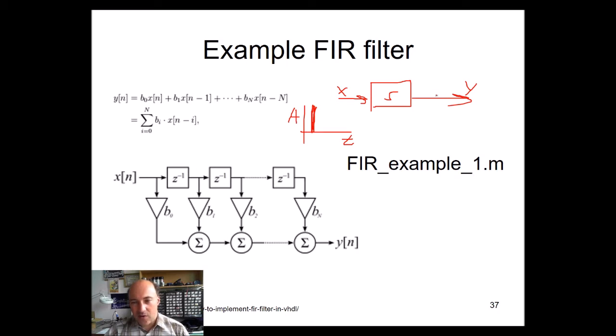And here on the output you are watching for what's happening. So here you have t, and here you have y, and you will see something like this, and then there will be some reaction basically. And for an FIR filter it's finite, so when your input signal is 0, after a specific number of samples, your output signal will be 0 as well.